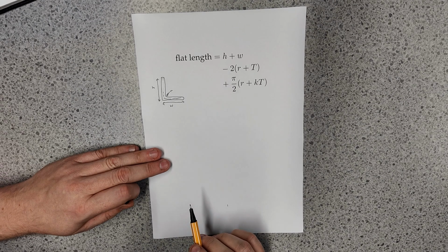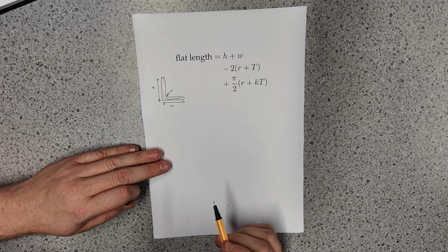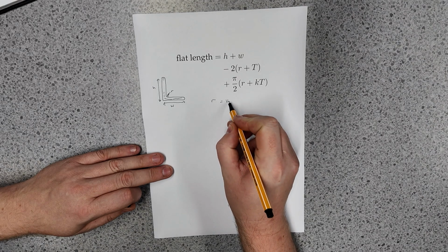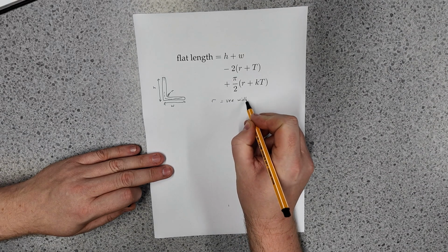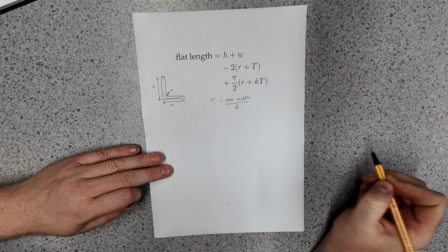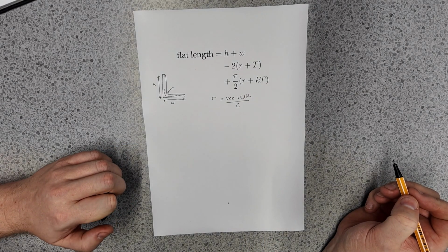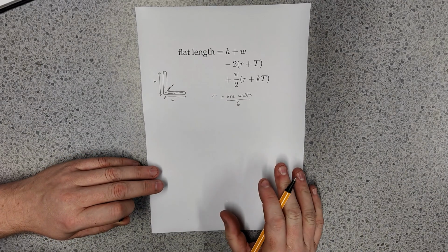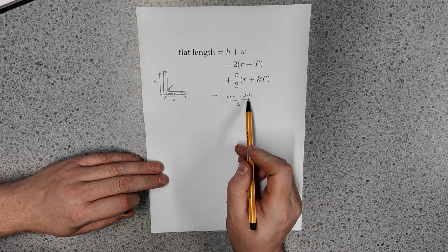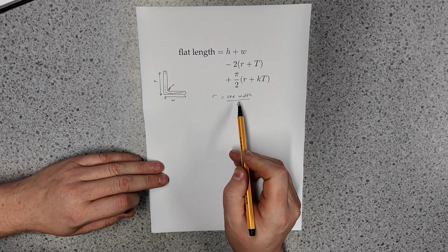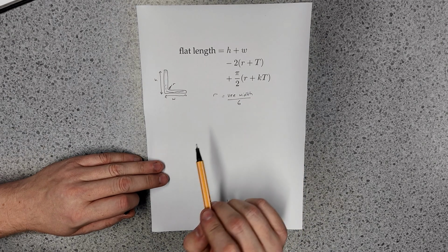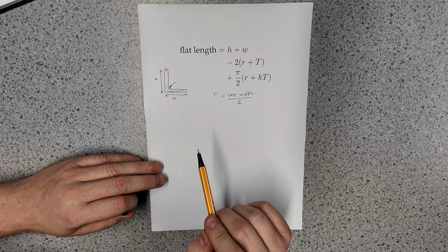So in this video we're going to try and compute R rather than relying on the rule of thumb formula. In the previous video I used the formula R is equal to the V width over 6. And one of the comments said, have you measured it? So the answer is yes, I have measured it, and for some V widths it's more accurate than for others. So I've done a series of experiments and measurements, and I've computed R and K. We're going to discuss several ways of doing that in this video.